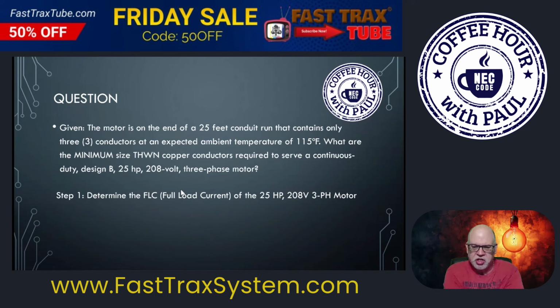All right, we're going to do this lesson today. And so here's our question. A motor is at the end of 25 feet of a conduit run that contains only 3 conductors at the expected ambient temperature of 115 degrees Fahrenheit. Okay, and we say 3 conductors. There's no neutral needed here, and it's using the conduit as an equipment ground, which is permitted by the NEC, whether you do it or not. In our example, it is.